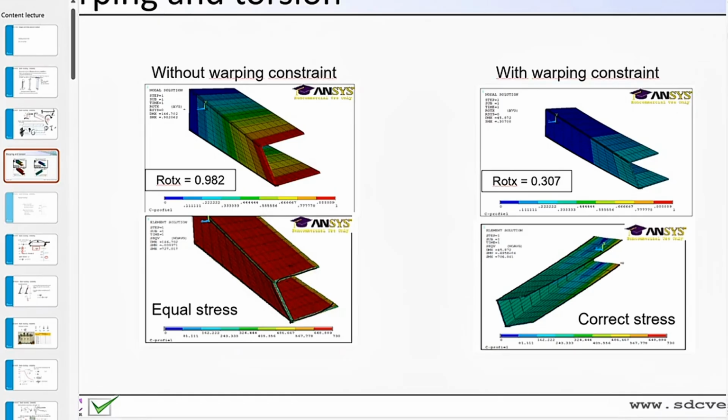So if you really need an FEA linear buckling analysis, make a plate model if you have something like open structures, because the stiffness cannot actually be reproduced with a beam element.